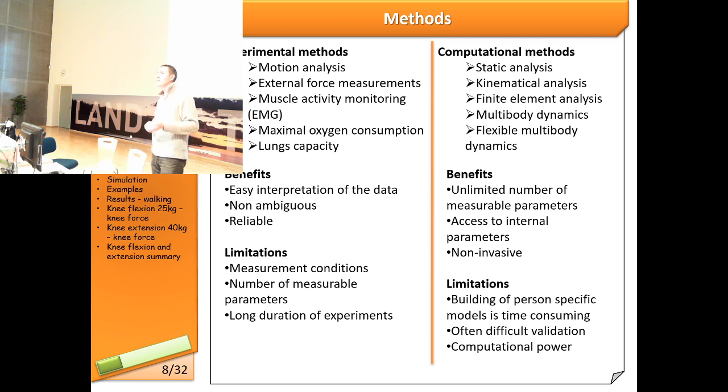You can do finite element analysis, and that allows you to get the information about stresses. So how much some parts are loaded. And of course, this is good in a static case. You can also have some simulation in the finite element software, but that will be quite computationally expensive, but it's possible. You can have multi-body dynamics, which shifts from a model compared to finite element, where you have lots of elements that you have to solve and small time steps and really small time windows that you can analyze.